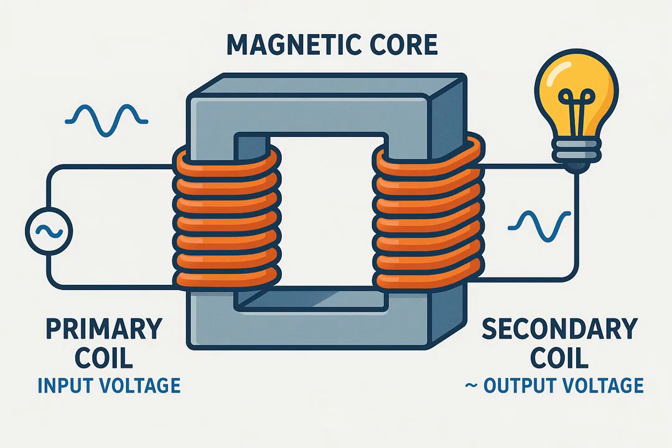What is a transformer? A transformer is an electrical device used to change the voltage of an alternating current, AC, either stepping it up or down without changing its frequency. It works based on the principle of electromagnetic induction, first discovered by Michael Faraday in the 19th century. There are two major parts in a transformer: primary coil, connected to the input voltage; secondary coil, connected to the output voltage. Both coils are wound around a common ferromagnetic core.